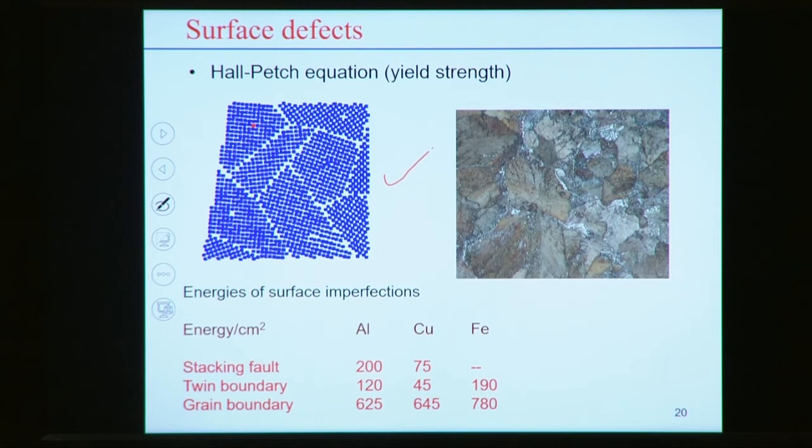Now we can find this out. We can see the actual structure of a material. If you see that clearly, one grain is separated by the grain boundary, and that grain boundary is considered a defect. That defect is mostly represented in terms of dislocations. If you look at this figure, the schematic representation of the grain boundary, the orientations of the grains are different because they are separated by one specific boundary. So these are the representation and explanation of the different kinds of defects that exist within the crystal structure itself.